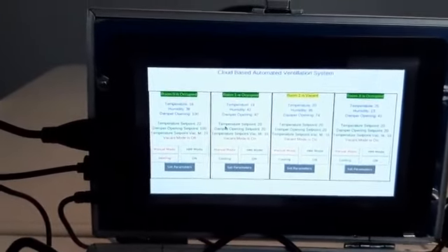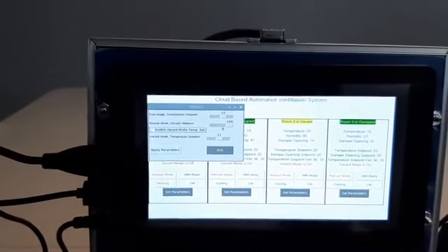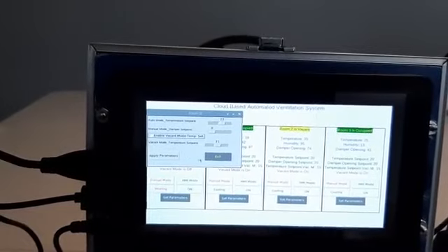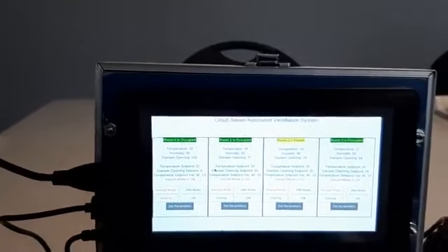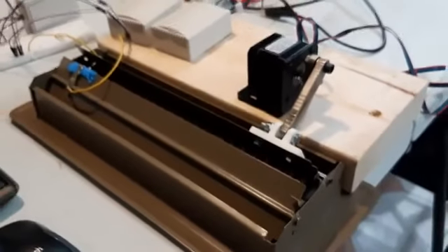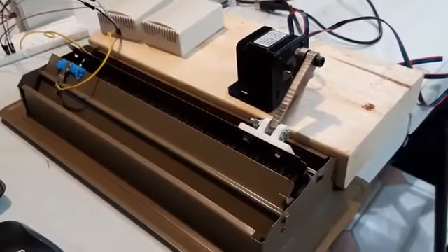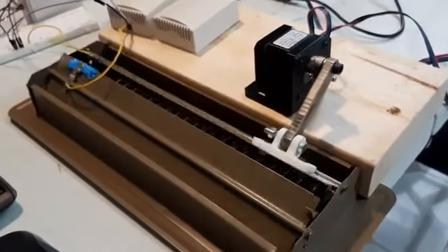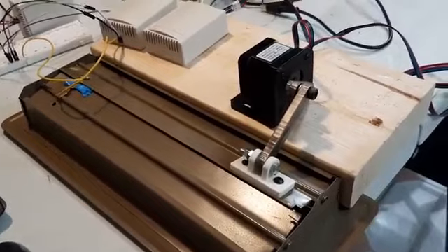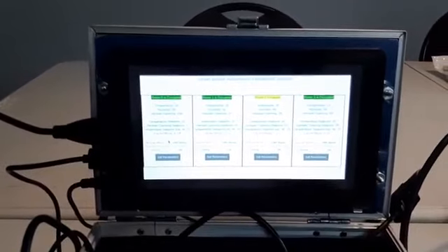I want to try to close the damper now by changing the set point in manual mode to 0%. Okay, the damper set point is 0%. We look at the damper again, waiting for it to operate, and it's supposed to be fully closed now. There is a switch here which gives us a fully closed contact. The damper is fully closed now. Okay, so it works in manual mode. We can operate it in auto mode.